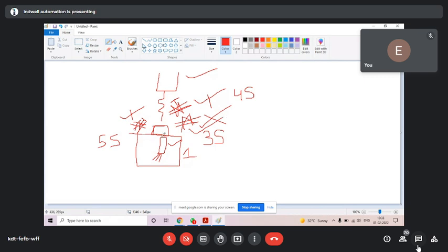So what will happen: as we put the job on the workstation, suppose I0 gets on. As I0 gets on, a timer will run for 1 second. As 1 second is over, the timer will generate one confirmation signal that we call the done bit. So the 1 second timer done bit, NC, will switch off this valve. And the 1 second timer done bit, NO, will switch on this output.